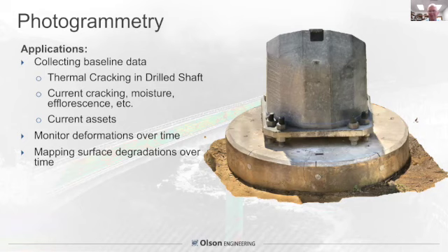If you look at this, you can get a better sense of the depth of, in this case, a cracked drilled shaft foundation at a transmission tower. You get a better sense of the severity of the cracking damage and the conditions on the surface. The files are quite large. The files can be saved to monitor deformations over time and see how the surface degradation progresses over time. So it's a good baseline as well as a good image to overlay on. The resolution is so high ultimately that you can't even show it on a computer screen. So it can be zoomed into, of course, but the fine detail is there.